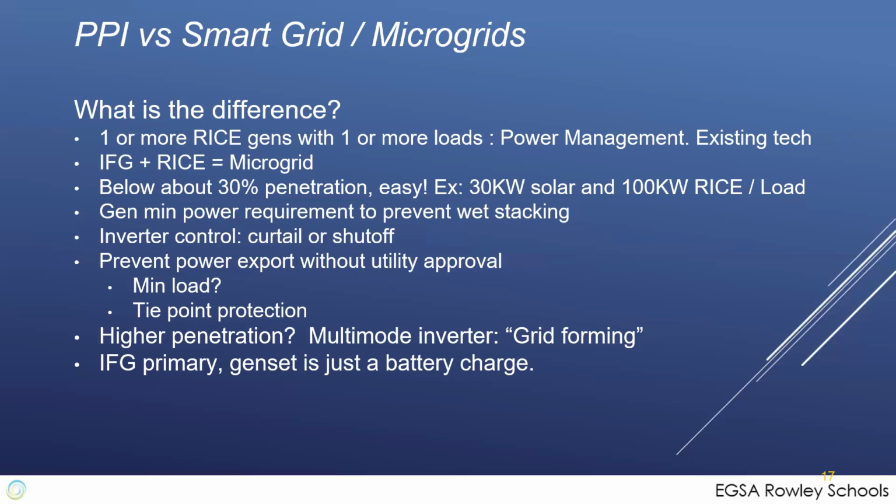But as it starts to get to higher penetration, to the point you can start pushing the generator around, or you can get the generator into minimum power, or you start having frequency or voltage issues, then you need to take more control steps. That's when it becomes more critical and you have to do more controls. But small amounts of power on the grid, like it has been in the past, it's not a lot of control necessary. Only when you get into bigger percentages does it become a problem. And we've seen the bigger percentages in Texas and in California with 2 recent incidents.